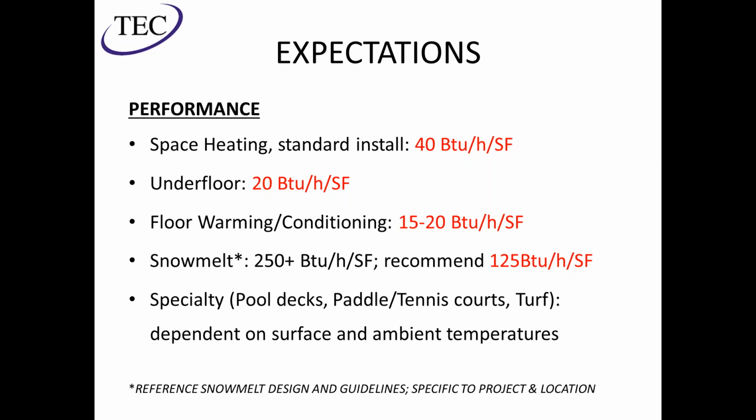One thing I'll note on that really quick is when we're doing a high-end residence, for example, a lot of times these houses will have multiple furnace systems in them, and then they want to install a boiler that can do this huge radiant output. But the fact is those are going to be overlapping. So either take those into account in your design of the furnaces and decrease the load, or decrease the output necessary for the radiant. Otherwise, you're going to have basically two redundant systems, which again, maybe that's what they want, but just make sure you're very clear with the expectations of the system.